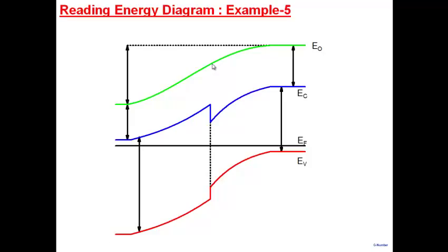Two different semiconductors, because for a semiconductor, electron affinity is the same, irrespective of what doping you do, what voltage you apply, electron affinity is a constant. So I see here that when I go from here to here, I see a discontinuity, it indicates a discontinuity in electron affinity. So it indicates that I have two different materials here. Okay, so that's where these discontinuities are coming, and similarly a discontinuity there is coming.